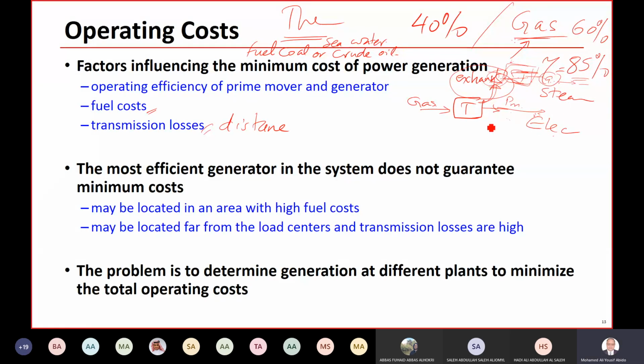Here you use the steam directly, but sometimes you can use the steam to also generate electricity. Cogeneration means you can have electricity and steam at the same time. Of course this will increase the efficiency of the gas turbine, compared to just letting the hot gases go to the air without any benefit.